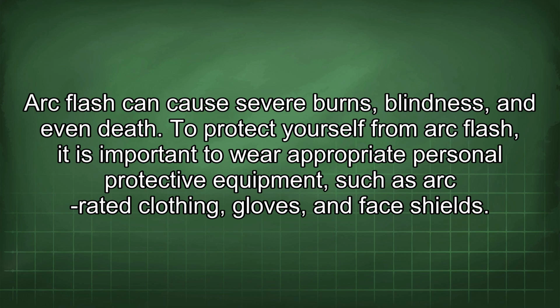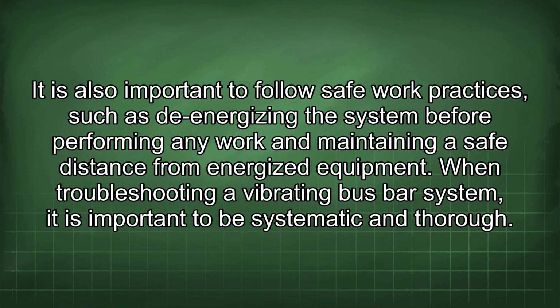To protect yourself from arc flash, it is important to wear appropriate personal protective equipment, such as arc-rated clothing, gloves, and face shields. It is also important to follow safe work practices, such as de-energizing the system before performing any work and maintaining a safe distance from energized equipment.